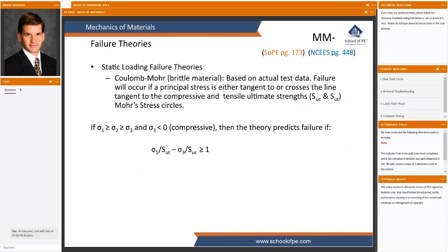One thing I will point out is that some of these failure criteria are based on yielding, and some other failure criteria are based on ultimate strength. Interestingly, the ones that are based on ultimate strength are said to be used for brittle materials. If a material is brittle enough, then its ultimate strength is approximately its yield strength anyway. They just don't yield much before they break. That's the hallmark of brittle things. So just pay attention when you're using the various failure theories, whether they would like you to compare to the yield or the ultimate. It's a common detail that you could overlook.